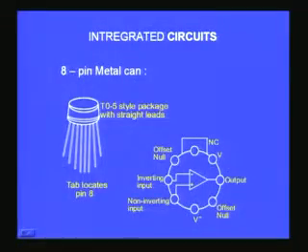Otherwise it is very difficult for us to use in the lab. So here you have got 2 different packages I have explained to you here. The one is the metal can package, which is basically like your SL100, with which I showed some demonstrations earlier, the TO5 transistor outline 5 style of package with 8 leads for the case of an operational amplifier, for example.